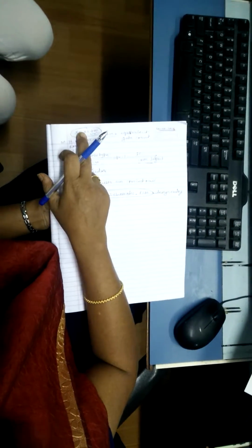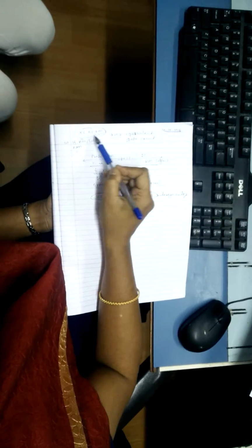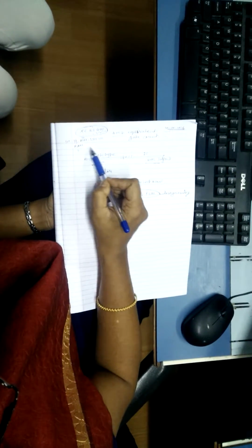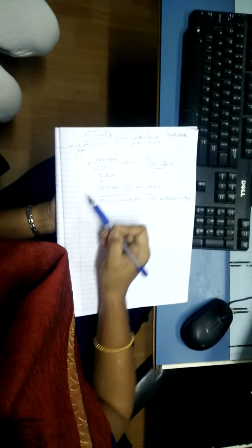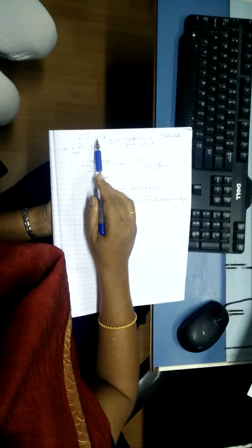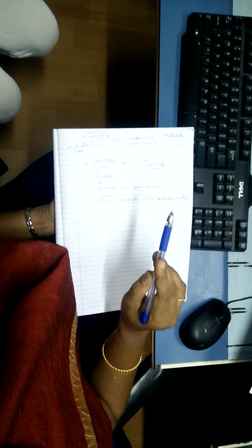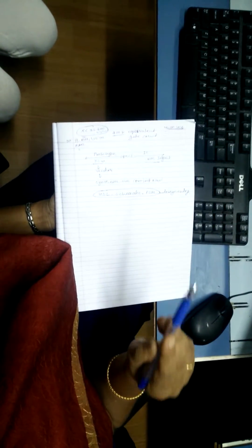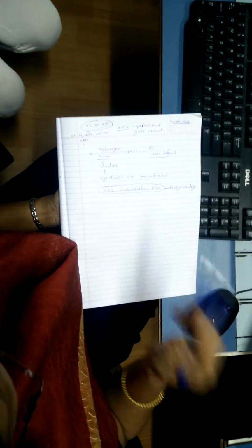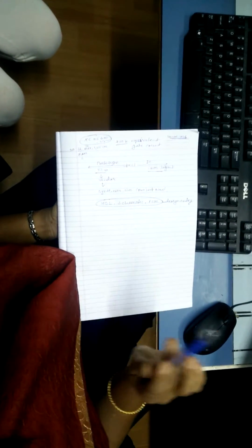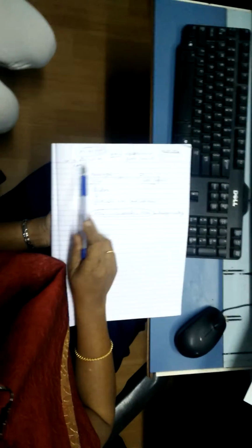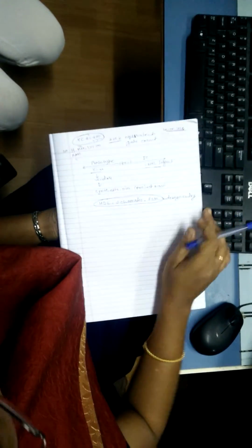No hardware is there right now, but on this IC, whatever resources are present in the form of these components, if they are converted into universal gates, you will need this many gates. This is the meaning of 400. It is not a simple 400 number, it is 400K. 400K equivalent gates are there inside the IC. Actual gates are not present in the FPGA, only whatever is present in terms of these components. So this is the meaning of this device number.